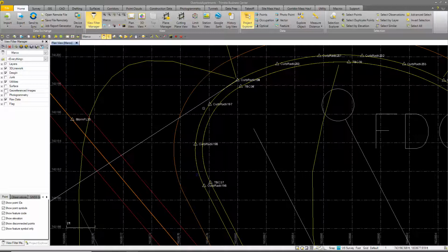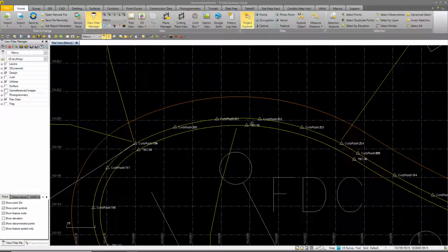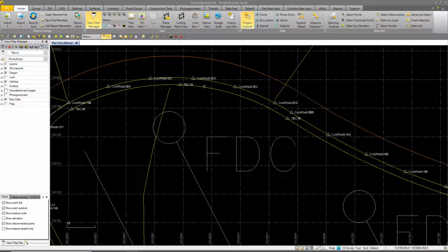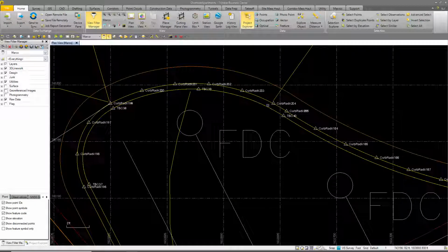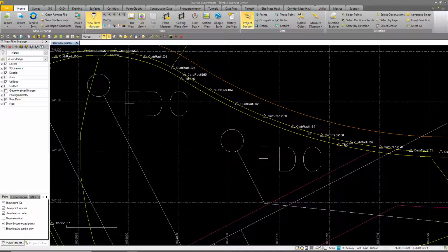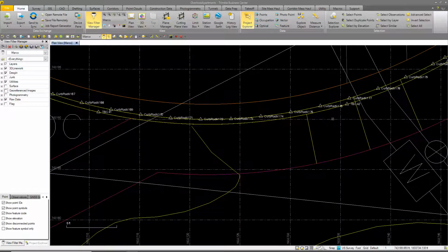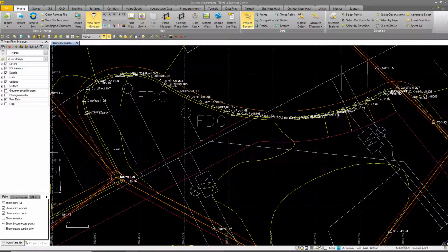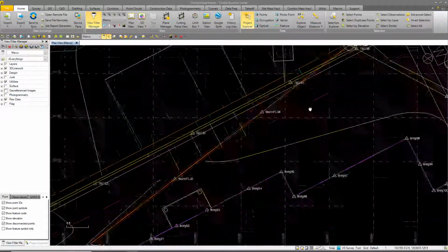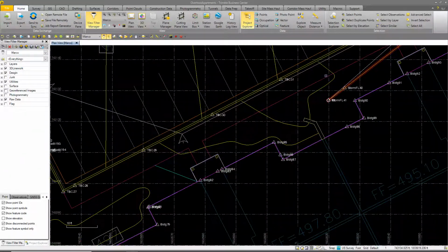And then this radii point for all these curb radii are going to give you a way to follow that information to take you and line you out for face of curb, and then there's another top back of curb point. So what you're going to do is use these for layout and also to verify grading information.